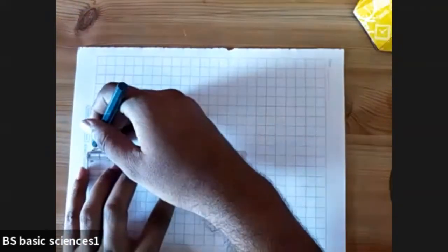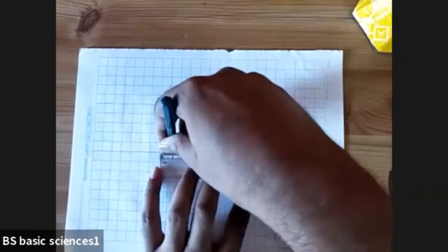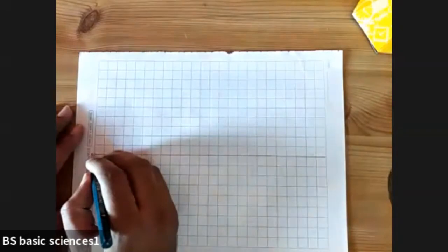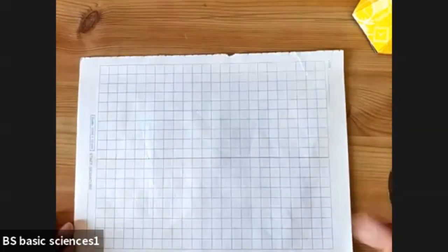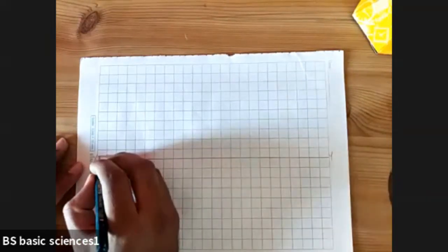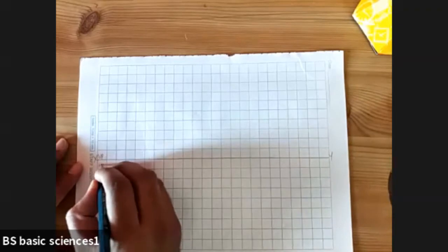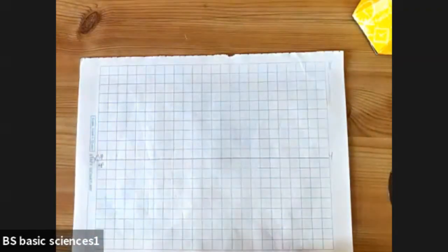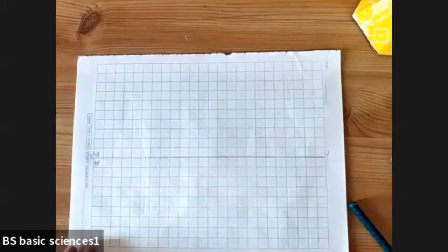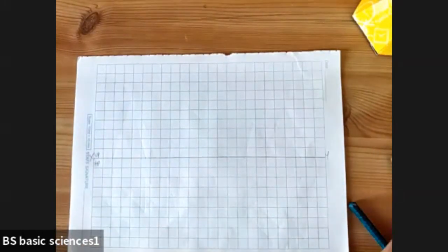Draw the XY line. Mark the points. This is your X, Y, the vertical plane and the horizontal plane. In the vertical plane you can see the front view, and in the horizontal plane you can see the top view. It's a pentagon pyramid and it should be edge resting. So draw the pentagon, rotating your page like this.